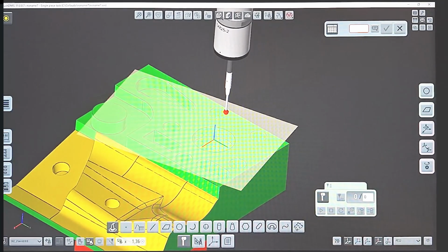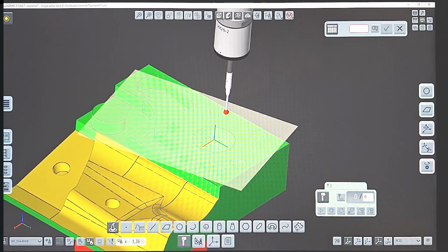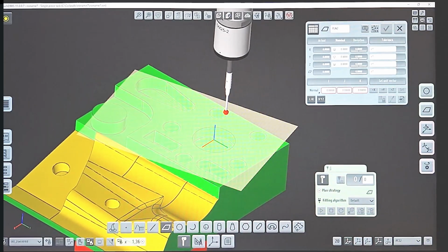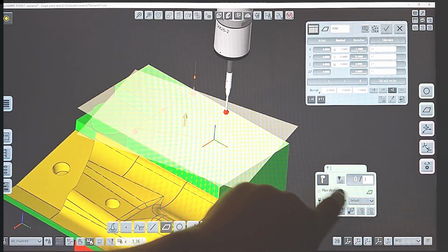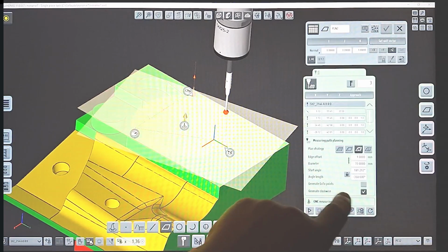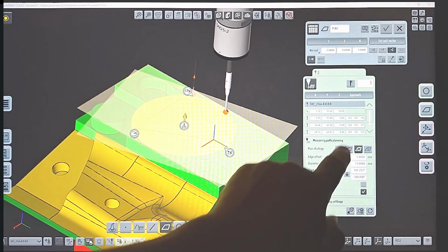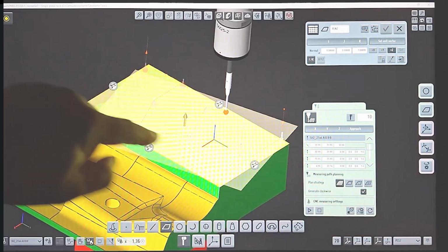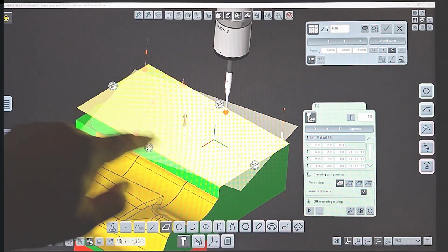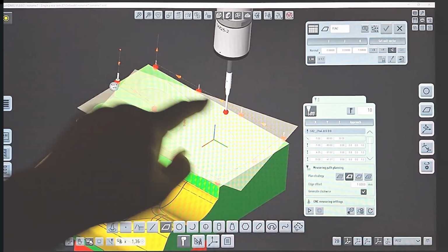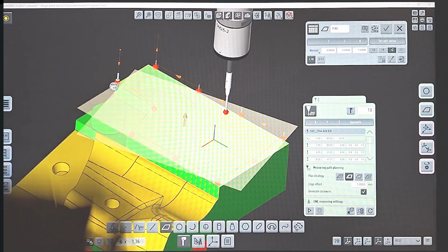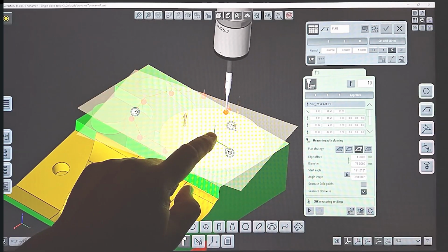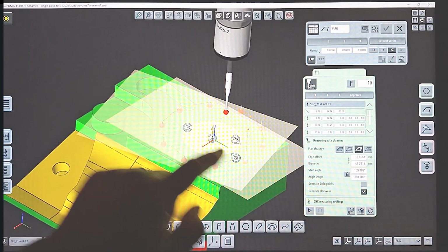Let's see another example. In TouchDMIS, we can create a feature and easily customize the way we want to inspect that feature. We select the plane. The default strategy that is proposed by the software is the last one that we used, which is a zigzag point, where the points are distributed ignoring and excluding the holes. The boundary, following the edge of our feature, or a circular path. The circular path can be dragged and customized. So we can decide to distribute the points on a circular path.